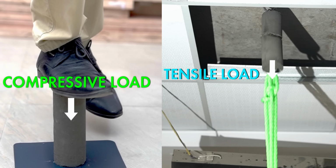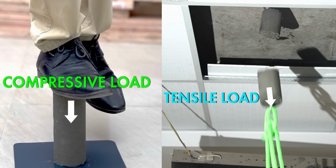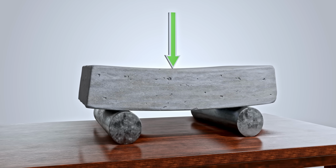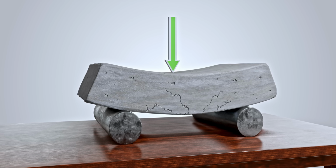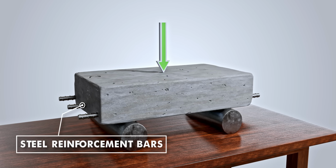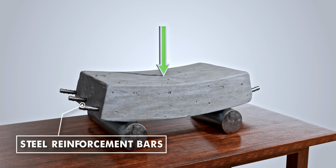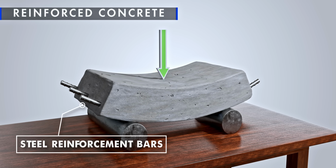This experiment proves that the concrete is good in compression, but quite weak in tension. This weakness means the bottom portion of the concrete block, which is under tension, can easily develop cracks. So what's the solution? Introduce steel reinforcement bars to the regions that experience tensile stress. Steel is excellent at handling tensile forces. The structure we've just created is called reinforced concrete.